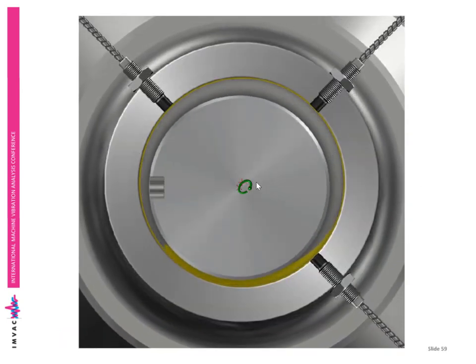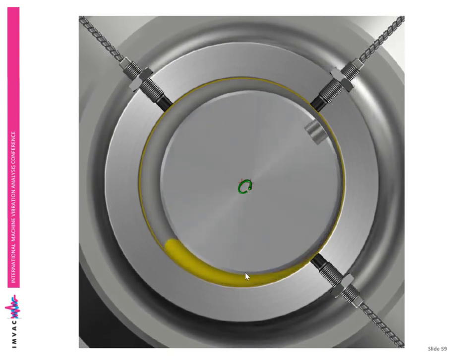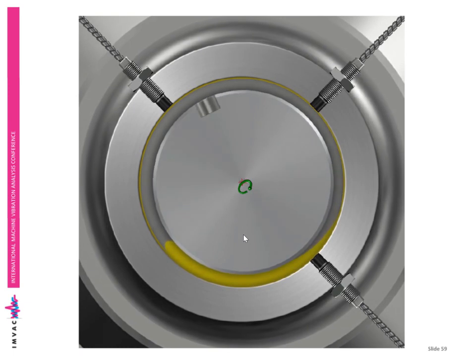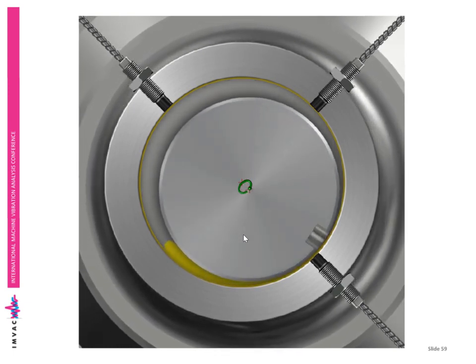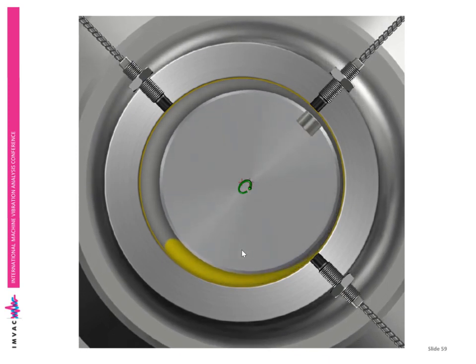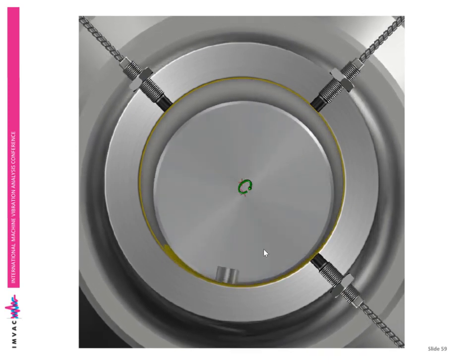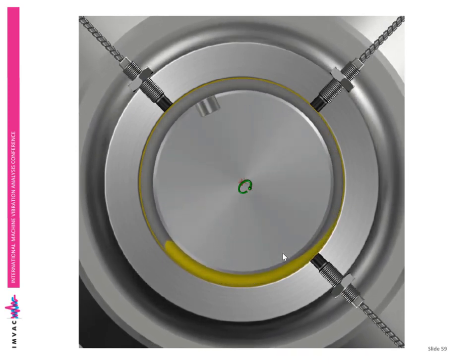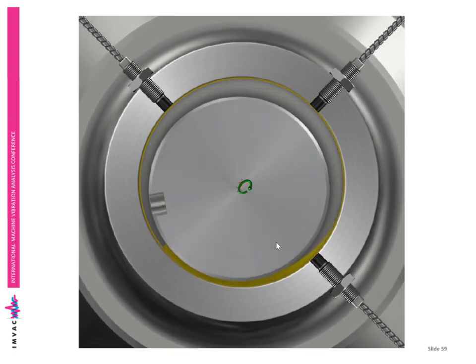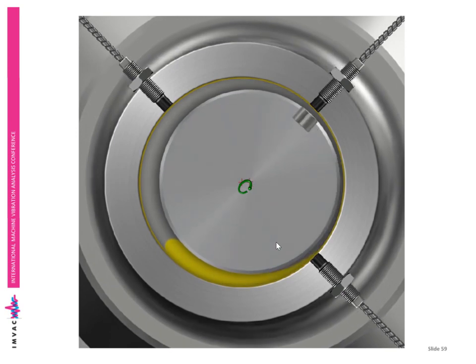The idea is this shaft's turning around and it's sitting nicely on this film of oil. It's supposed to be in a certain location within the bearing. For example, with the shaft turning in this direction, it's supposed to be just off center to the right and sitting in this area. It's a bit hard to see from that animation because I've exaggerated the motion so much, but that's what it does when it's stable.